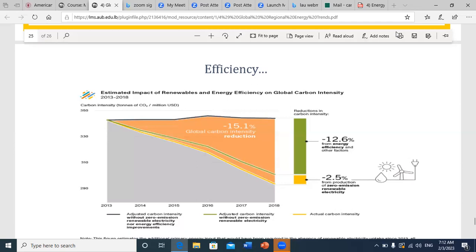So we can, let's say, circulate a fluid in a heat exchanger that can absorb the extra heat of these PV cells. And this will lead to enhancement of their efficiency, plus at the same time use of heat in a useful way, because this heat was rejected and was a waste. So by using the waste in an appropriate way, we can really increase the efficiency, because at the same time the performance of PV cells is better, plus we are using waste heat in a useful form.